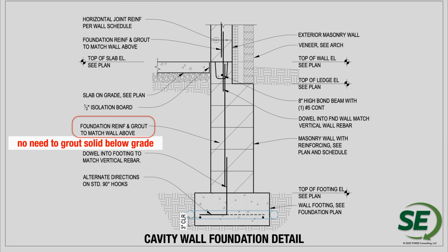Last, we're going to move into foundation wall designs. Foundation wall designs are usually, especially for a stem wall, not going to be overly critical because the structural demand on them is not too high. Really, the walls become relatively thick relative to the elements that are sitting on the wall. So it comes down to a compatibility issue. Recognizing that the stem wall is going to be there, it's going to have multiple layers of design above, whether it's a masonry wall, cavity wall, or whatever different types of elements.